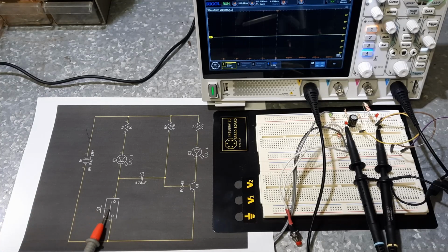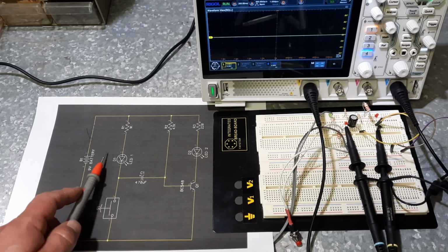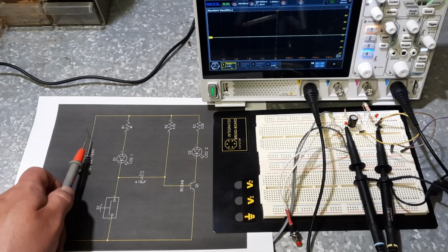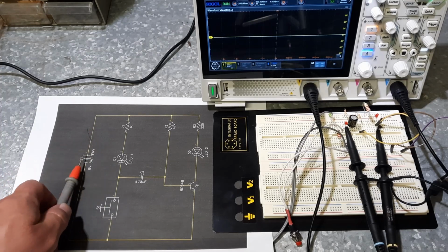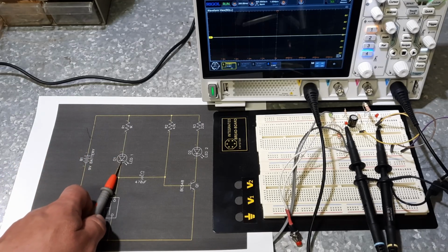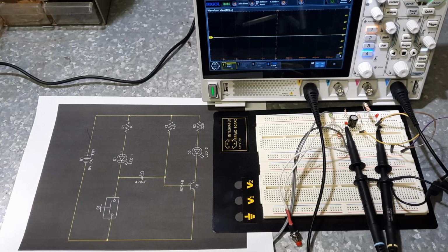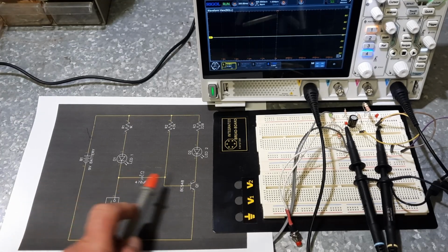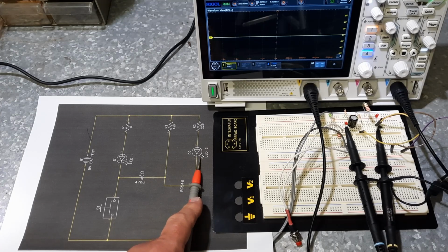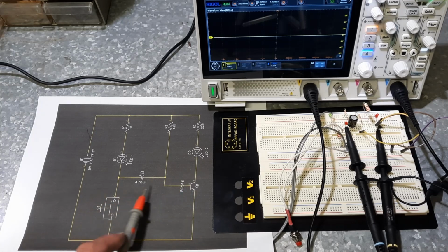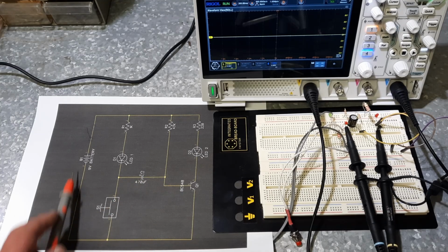What is also going to happen when we push this switch, it is now going to give this a path to ground, or negative I should say. So what's going to happen? There's going to be current flowing from here around. So LED 1 is going to light up. LED 1 will be on, LED 2 will be off. And so as long as I hold this button, that will stay like that, and it won't change state again until this capacitor has fully discharged.